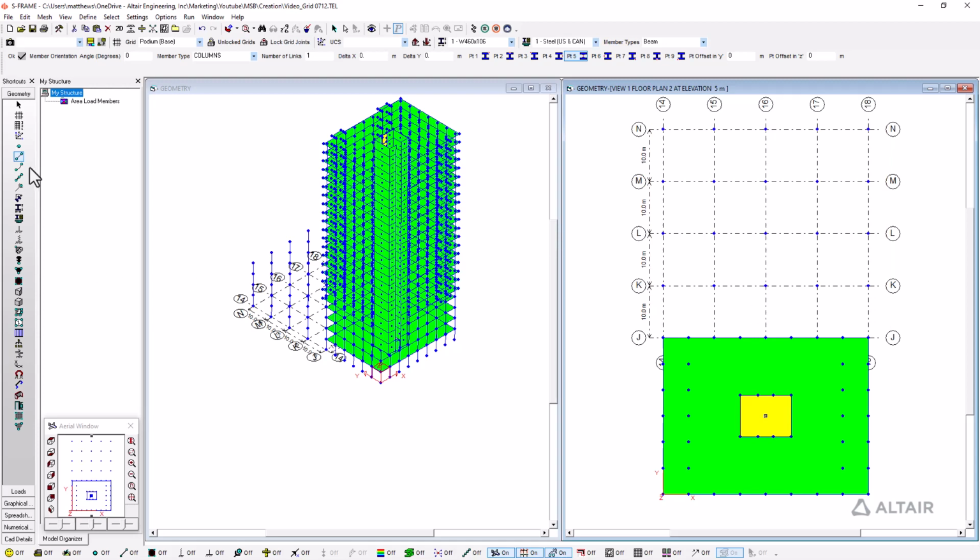And then I'm going to have some beams as well. So that's not something we saw as much of in the tower structure since we have flat slabs. But I'm going to use the beams in a girder beam, infill beam setup to support my composite steel deck. Here I'm going to change the section size, so I'm going to go with this W410 by 54 section, and we're going to have our girders essentially running in this direction.